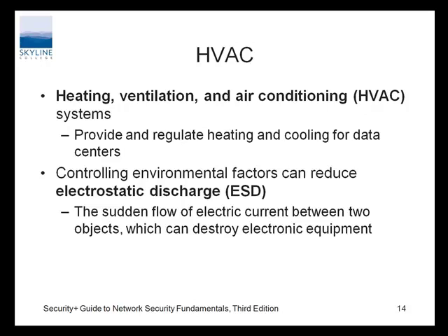It damages the insulation of the electronic devices. It may not fail instantly. That's why they tell you, or hopefully still tell you, that if you do this, you may have weakened the area around the device, and it may fail later. It may fail immediately, it may fail in six months, a year, whatever else. But electrostatic discharge does do damage.